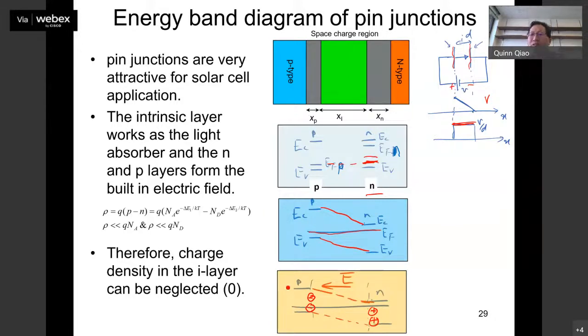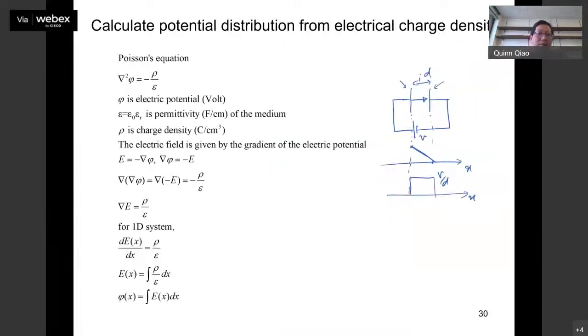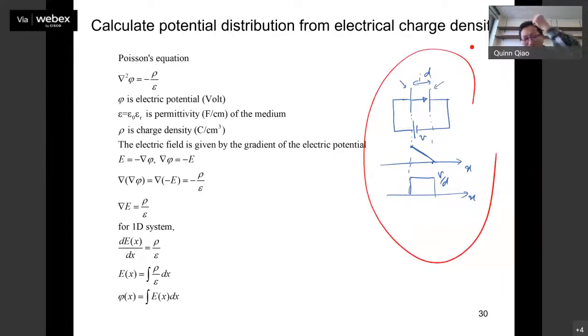That's different from the capacitor I mentioned earlier, because for a capacitor you apply the positive on the left side. But here, this positive is made from the inside, because the inside lost negative charge, so only the positive ions are left there. So that's how you see the electric field is from right to left. The potential will be higher on the right side, positive on the right side, negative on the left side. This is almost equivalent to a capacitor.